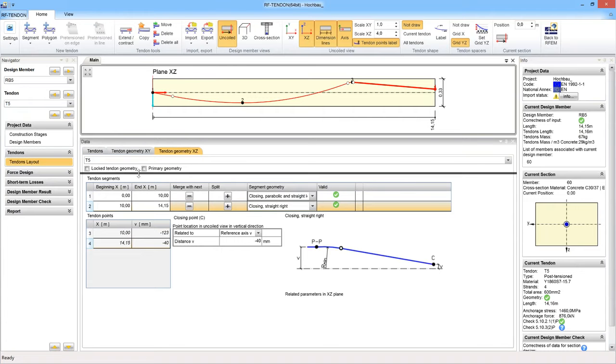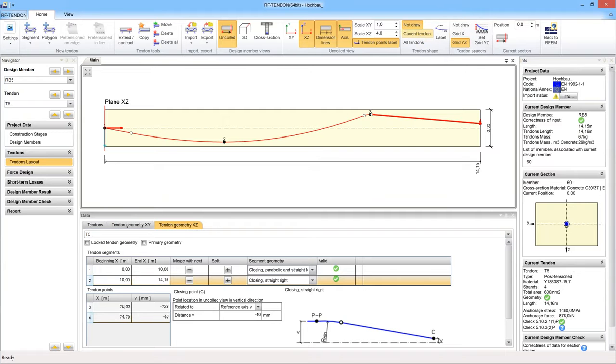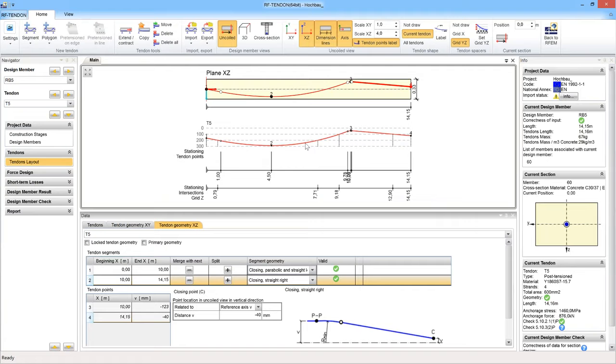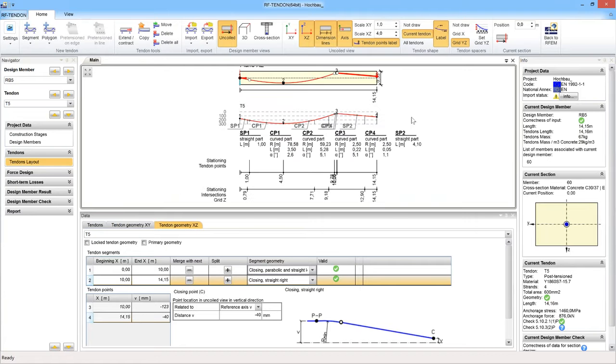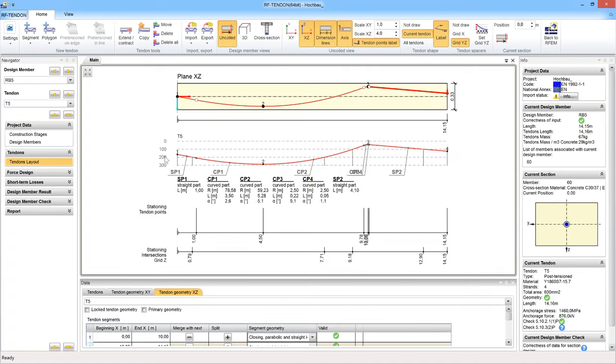The last thing which I wanted to show here is the drawing of the tendon along the length. Maybe I can switch on the labels, and then you can see that, by defining these levels from the bottom of the beam, especially from the formwork, I can define the distance of the spacer which should be placed with specific depth. For example, the spacer which has 300 millimeters will be placed here at 9.18 meters. So the program calculates it for you.